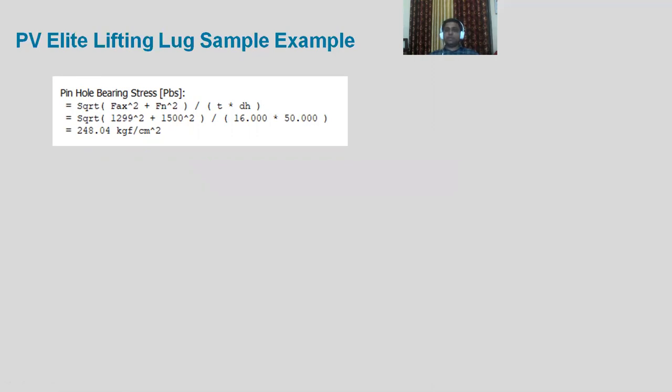And because of which force can the pin be under bearing, or the bearing force be coming, or the two surfaces be pushed against one another? You can see that there was one tangential force. That tangential force can move the pin along its axis, right? So it won't create any bearing, it can just slide the pin. But the other two forces, axial and normal force, can create the bearing. So here the resultant has been taken with reference to the normal force and axial force. You can see from here, axial force and normal force can create the resultant bearing force.